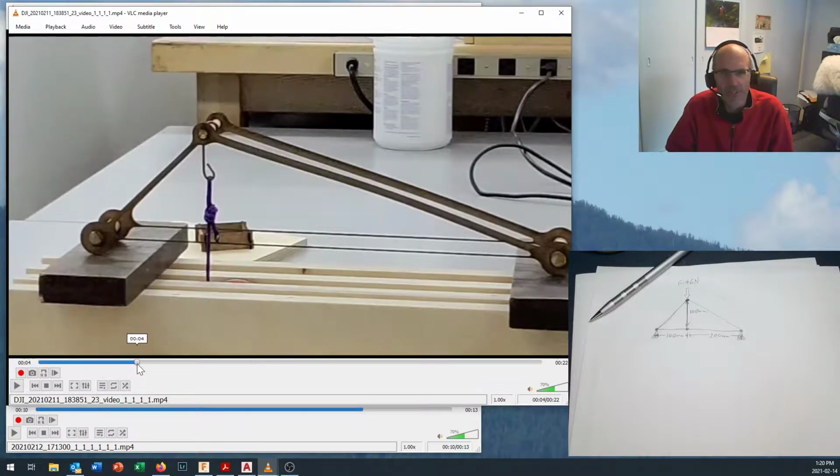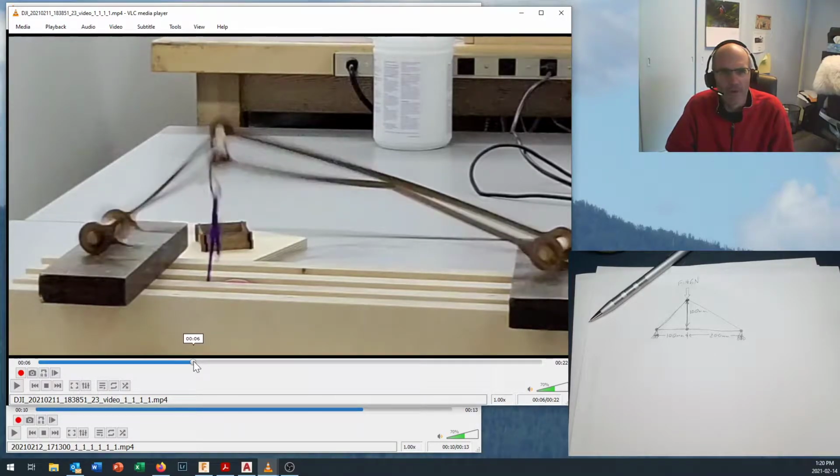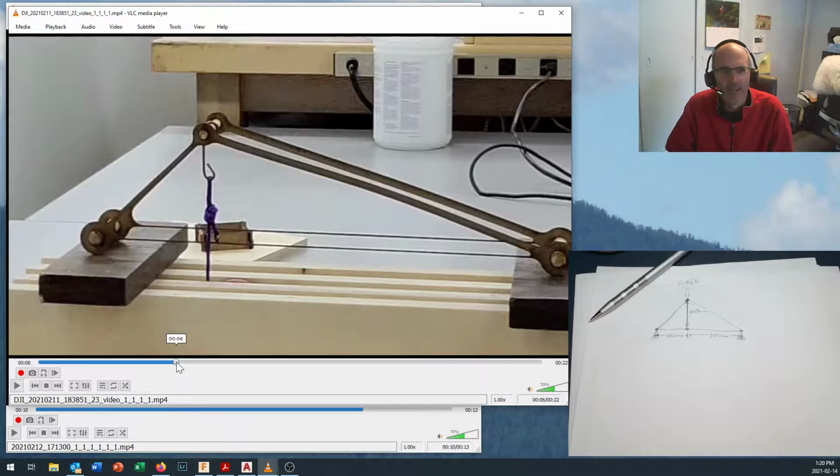Okay, we're just starting to go now. Look at that top right there as it comes over. It's coming out towards us. And there you can see the structure starting to go. We've got a buckling failure in the long compressive member closest to us. You can see it comes down and then it starts to pop out to the side or to the inside, just like this. And this part starts to come down here.